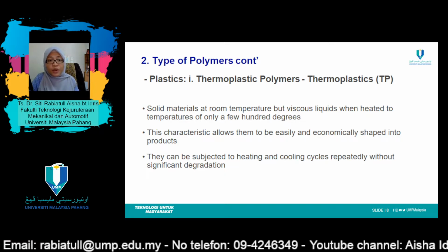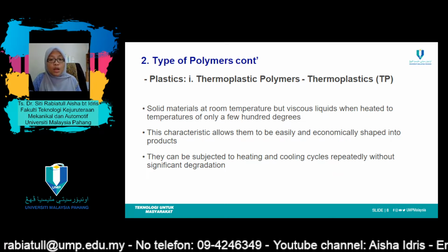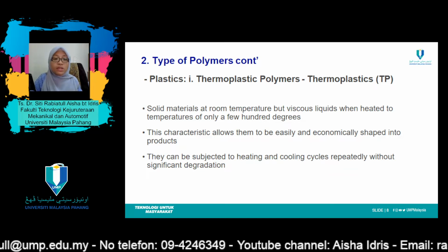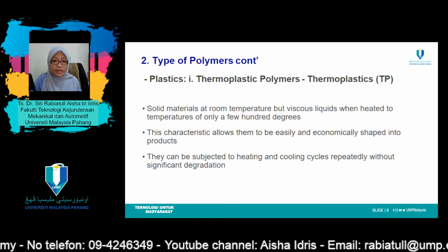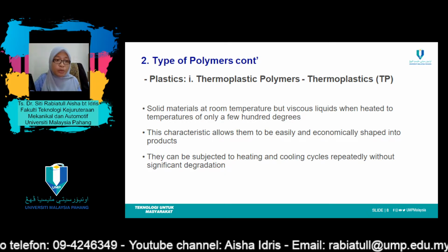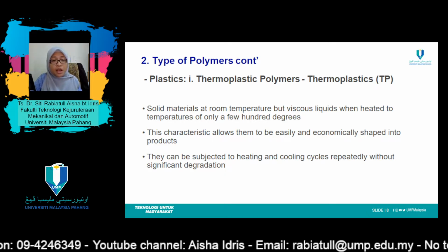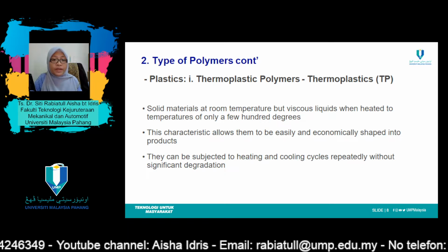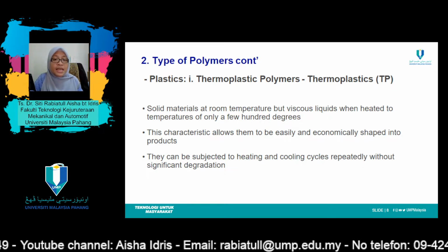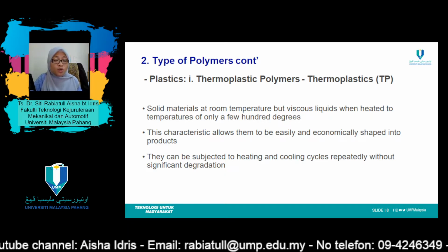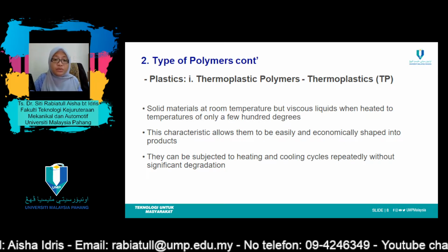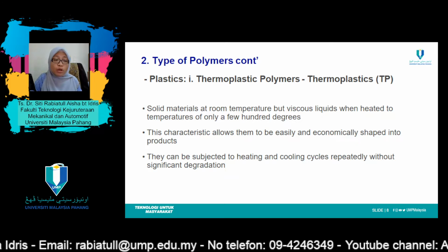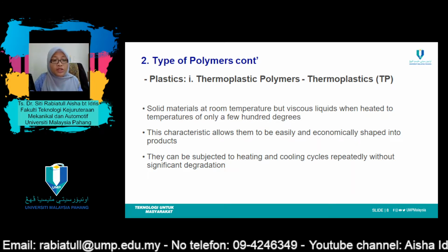Thermoplastics soften when heated and harden when cooled. These processes are totally reversible and may be repeatable. On a molecular level, as the temperature is raised, secondary bonding forces are diminished so that the relative movement of adjacent chains is facilitated when a stress is applied. Irreversible degradation results when a molten thermoplastic polymer is raised to a high temperature.